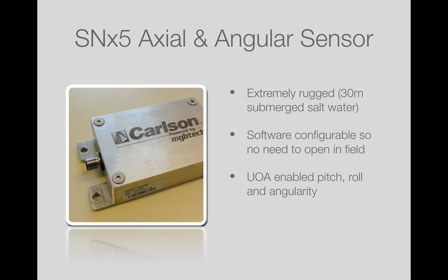It also is able to emulate some other sensors. So if you're using a particular brand of sensor, there is a possibility that we can remove that sensor, put this sensor on, calibrate, and continue working, because to use multiple brands of sensors in the same CAN bus line, we need the protocol and communication to be the same. So this is possible, but we would need to check on a per case basis.